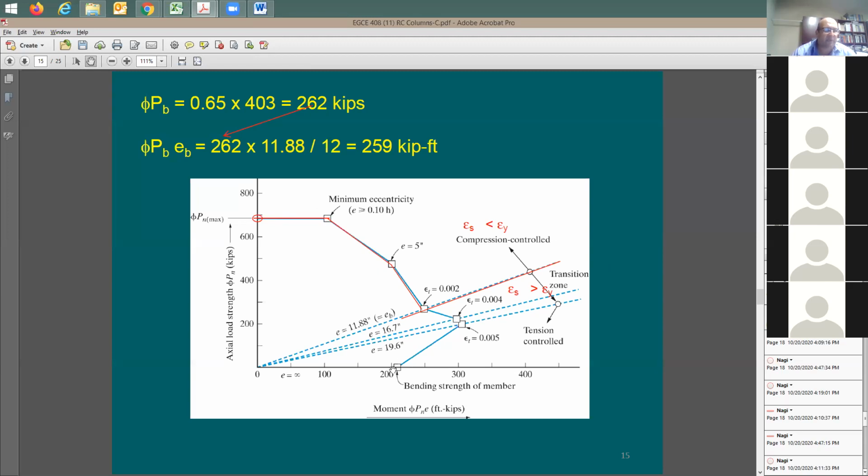Someone's going to say, how about this point? This is the easiest point actually, when you have no axial load. This is going to be a section with compression reinforcing, and you should be able to solve for this. We have done this before, right? So I know this point is an easy point. Why? Again, because the axial load is equal to 0. So you're going to be doing a section with compression reinforcing. This is all you need to do. It's going to be a simple problem.